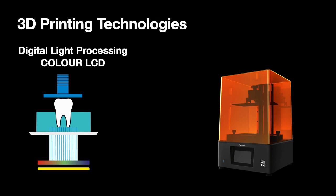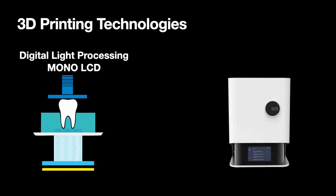So as you can see here, the light is incident through filters into a resin vat, creating layers after layers of the final product. Now, this technology is very difficult because the life of the LCD tends to reduce very quickly. So the next step was to create a mono LCD where the light source created spectrum-wise production. So you used only the UV spectrum, which is most predominantly used in 3D printing. However, the filters to create the image layer still continue. So that still creates a lot of energy loss. Plus, there is also some sort of light leak.